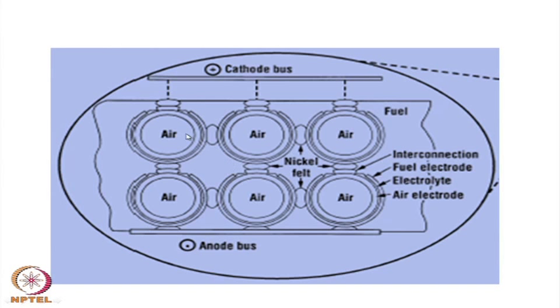This is the assembly by which the tubes are finally put together. This one can have stacks, so you can see this is the cross section of the tubes again, and this is the interconnect. So, the cathode is connected to the outside of the next cell. The outside is anode here and the inside is cathode. So, this is how the interconnect works.